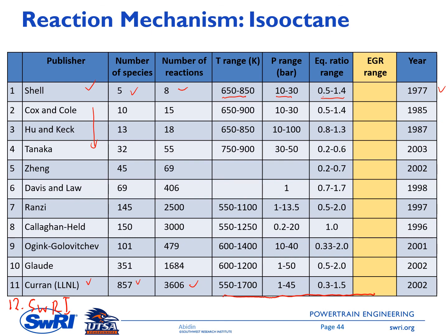Actually, we developed this one in, I think, 2017, but we needed to hold this reaction mechanism for 4 years because of the client who supported this research. So this HEDGE mechanism is good for gasoline combustion under a very high EGR condition. So here we might have around 30%.